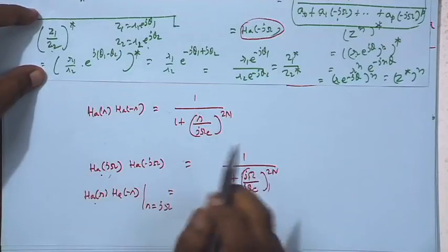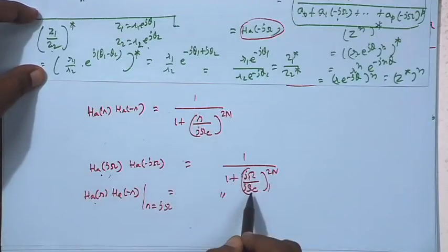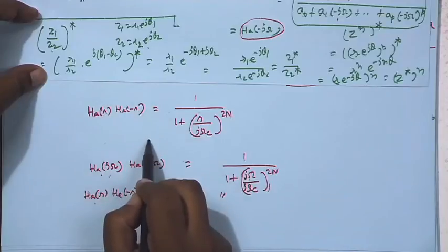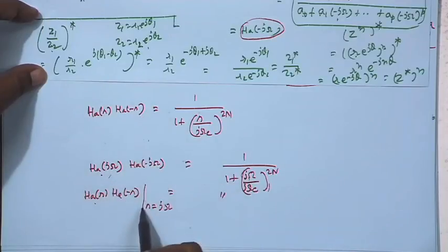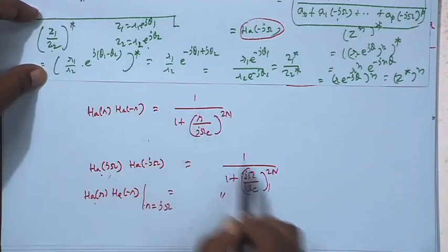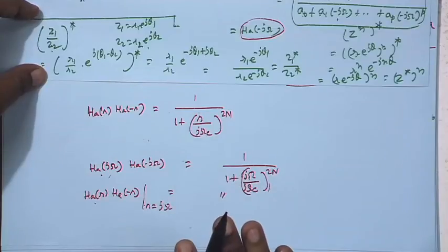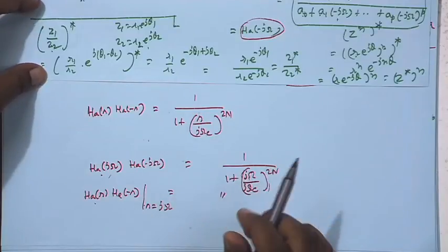All right, because now if you put s equal to j omega, you get back this. This is the left hand side, you put s equal to j omega as here, right hand side also is equal to j omega, you get back your original Butterworth function.